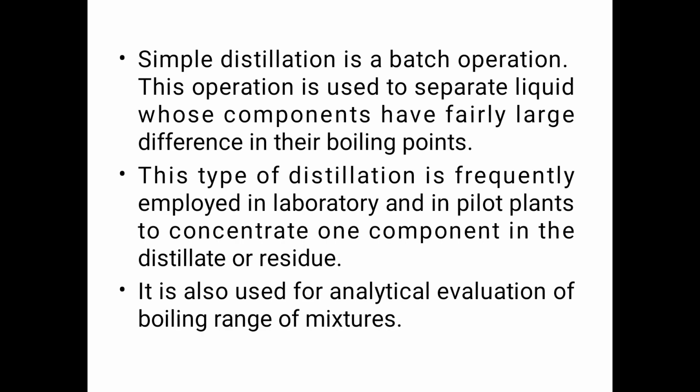Simple distillation is a batch process. It is majorly used for laboratory purpose, commonly used in the laboratory, not for industrial purpose. This operation is used to separate liquids whose components have a fairly large difference in their boiling points. We are taking two components, one more volatile component and another less volatile component. Only when the components have a very high boiling point difference is simple distillation employed.